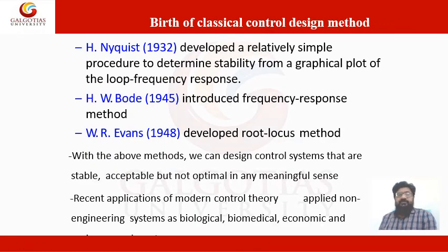Modern control system design methods begin with Nyquist in 1932. He developed a simple approach to determine stability by using plots and graphs, analyzing the loop frequency response. After 7 years, Bode introduced a frequency response method to analyze the response of an input to output, which is known as the Bode plot today. And Evans developed the root locus method to assess the stability of the control system.